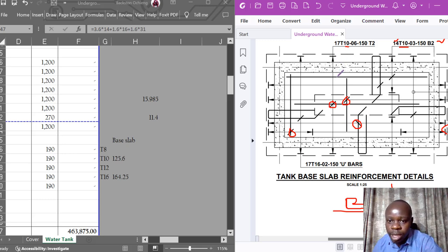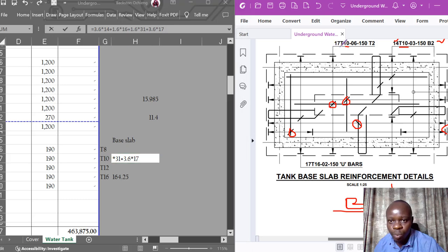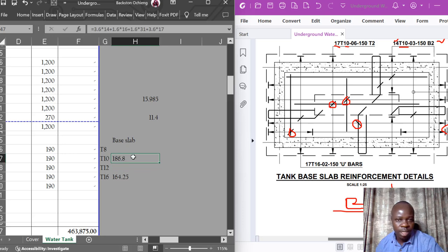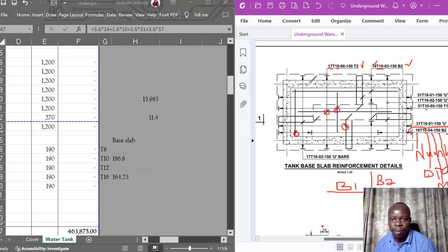So in this case, the reinforcement bar at bar number 6, we get to D10. Let's add it here. And when we do, the exact length we've said, we'll take the 3.6 meters. We'll multiply that by 17 because there are 17 in number according to this annotation. All right, so once we have that, bar mark number 6 is complete.